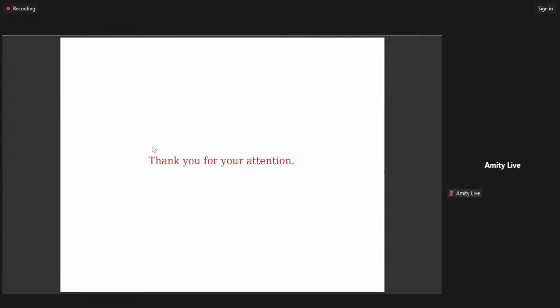I also varied the frictional parameters between the particles, from very smooth to very rough. It still holds, and interestingly, the exponent does not vary much in that case. So this is the first part of the study. The second part is to develop the flow rate expression, because now I have demonstrated that peak dissipation rate characterizes the transition boundary. Then I'll try to connect this shape and the outlet velocity profile and come up with the flow rate expression. That's it. Thank you.